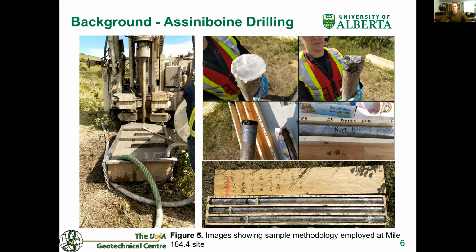A triple tube mud rotary coring system was used, where plastic liners were placed inside of the core barrels instead of traditional metal slips. Samples were collected directly into the liners, sealed using wax, capped, wrapped in plastic wrap, and then placed in wooden core boxes for transportation. The drilling technique was specifically chosen as marine shales experience rapid degradation in sample quality if not properly preserved. This also allowed us to preserve the samples for a longer period to be able to conduct X-ray scans and lab testing.